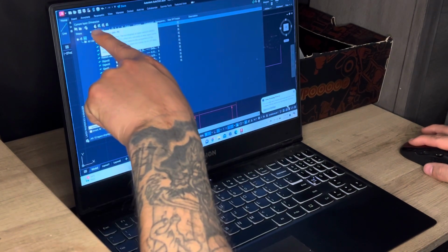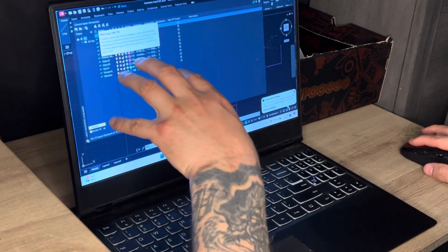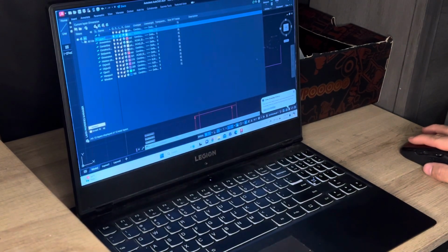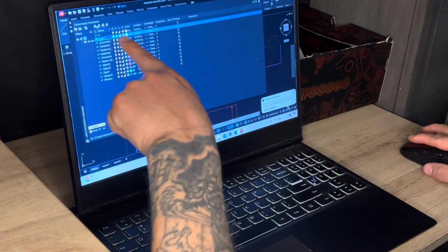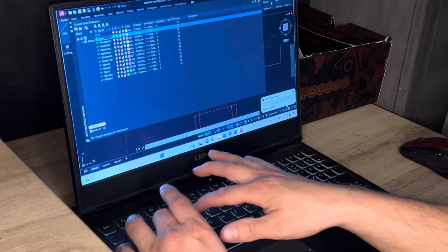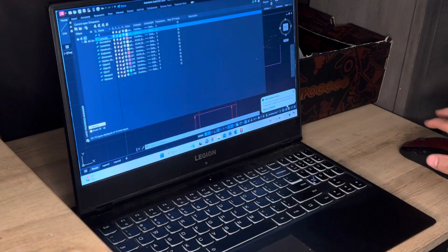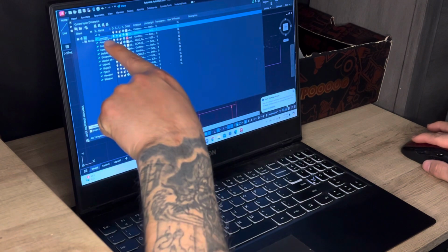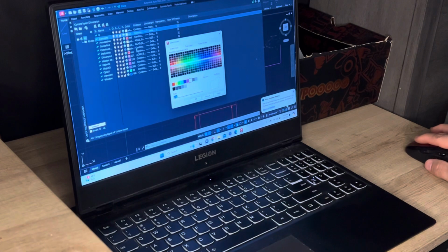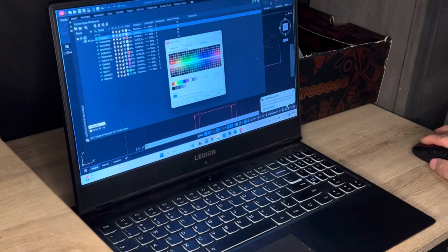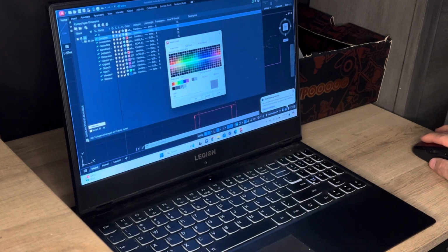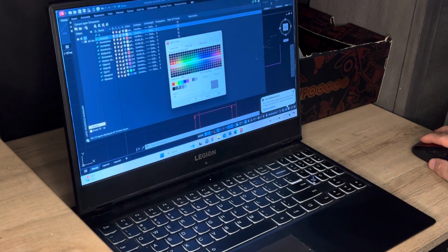I'm going to click this button right here. In my Manage Properties for my layers, I'm going to click that. That's going to be a new layer. It's going to let me name it right here, right now. See this one highlighted? I'm going to call this concrete. Now that I've named it concrete, I'm going to click over here on the color. My color palette's going to pop up, and I'm going to make it a medium gray. That's what I'm going to do.